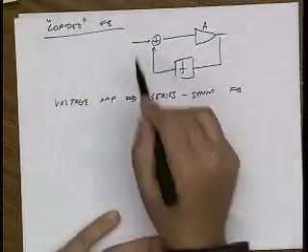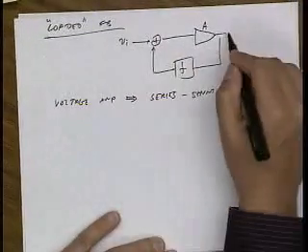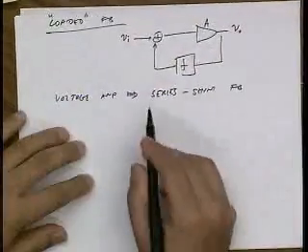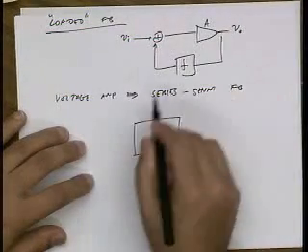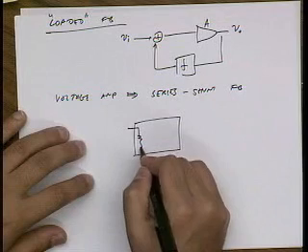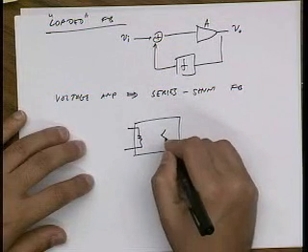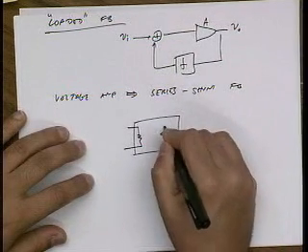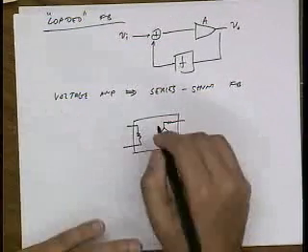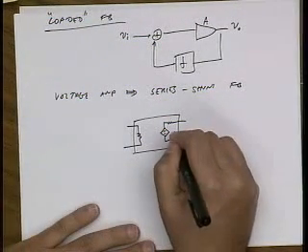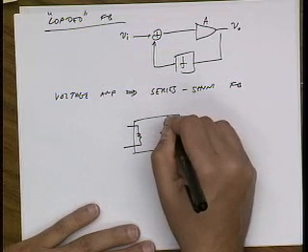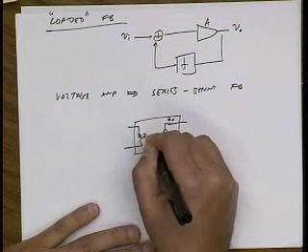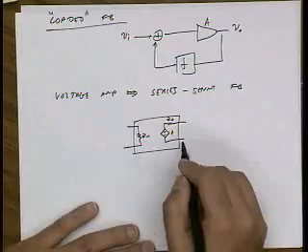That means that everything in the signal diagram, I want it to be a voltage. That means that my amplifier, because it's unilateral, there's only one direction for the gain. There's some internal gain A. It has some low output impedance, let's say ZO, and some high input impedance, ZI.